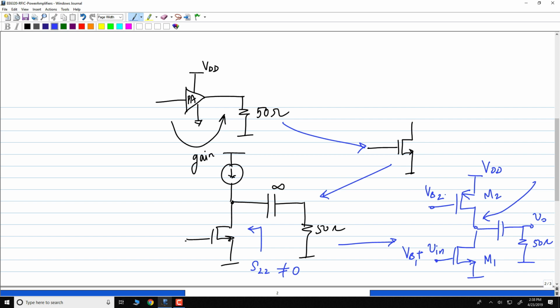This is actually a very bad circuit. You are basically taking two current sources, putting them together and saying what is the midpoint voltage, right? As you know from analog circuits, this is a really bad thing to do, because you are allowing the drain compliance, the dependence of drain current on drain voltage, to set the bias point.